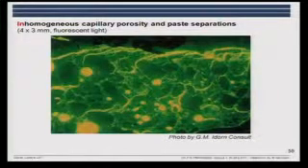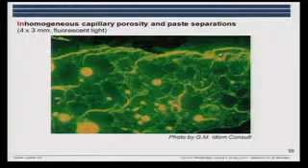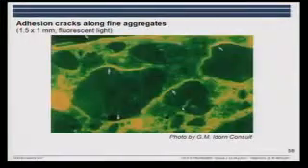And I'll show you some examples here, because here you can see some paste separations, and it's typically due to movement of the paste before it got sufficient stiffness. And here you have, well, highways through the paste or the concrete. Here we have adhesion cracks along the aggregates, also giving a very inhomogeneous structure.